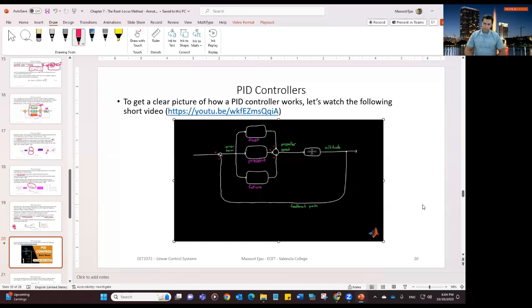And just like that, we've created a PID controller, proportional integral derivative. This is a versatile controller that uses the present error, the past error, and a prediction of the future error to calculate the appropriate actuator commands. These three branches each contribute some amount to the overall output of the controller, and as the designer, you get to decide how to weigh each contribution. You do this by adjusting the gain term in each branch. This is called tuning the controller.